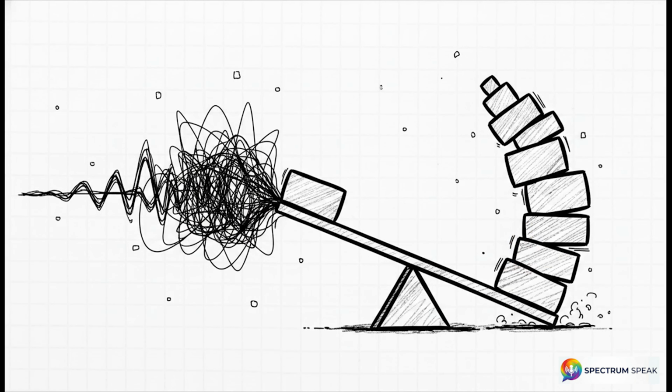And this is the massive pitfall that trips up so many engineers. If you're building a system or writing a script for this, and you forget to carry over that accumulator history from the previous bits, the whole thing falls apart. If your logic just defaults to the positive mapping every single time, your seesaw tips over immediately. The DC bias builds up, baseline wander kicks in, and suddenly your crisp signal degrades into total unreadable noise. You absolutely must track the past state.